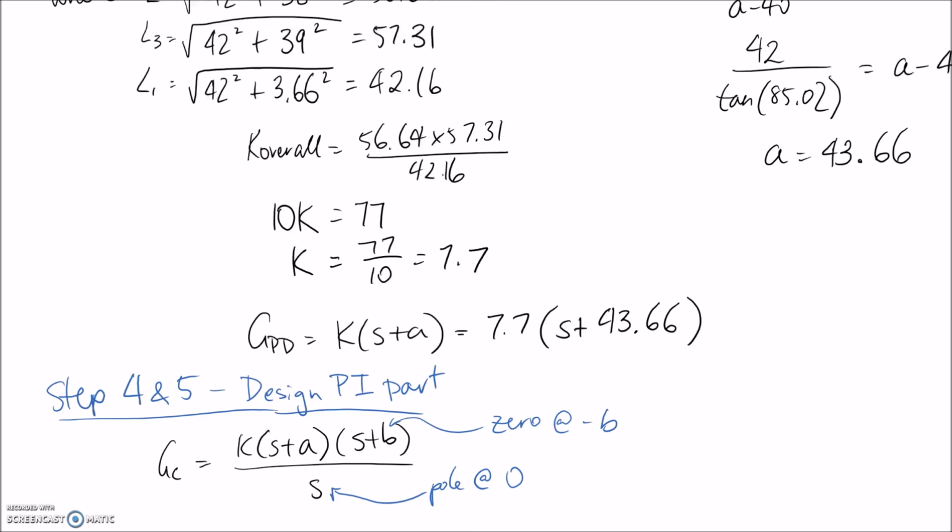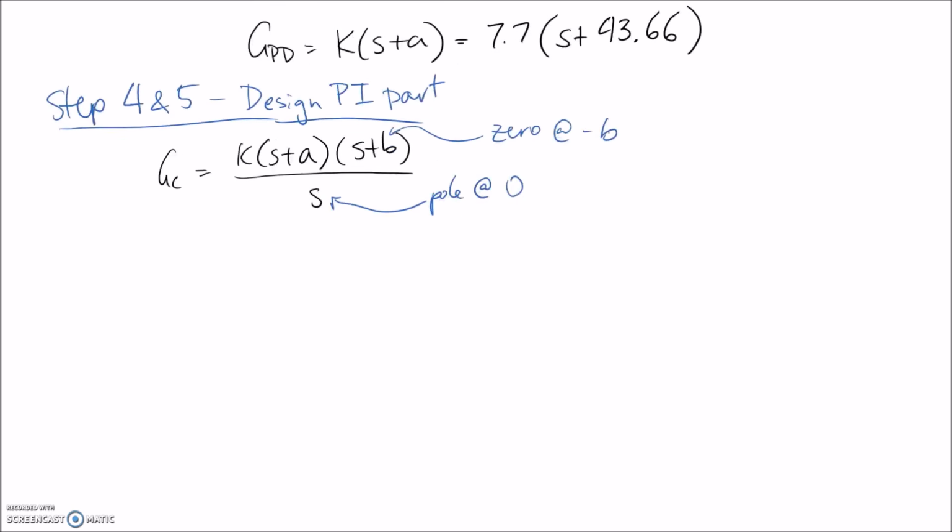So you have a bit of control over where you want to put the 0. This is because if you're using a manual method, you're not going to really be able to check the effect that it has. You're only going to be able to do that if you have MATLAB or something else that can simulate for you. So if this is an exam, you just have the option to pick a small number. So let's say I let B equal, I don't know, negative 0.1. We should be able to now sub that in to our controller transfer function, and it will be complete.